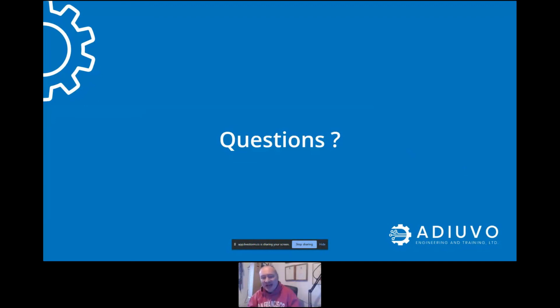Oh, that's a great question. Is there any advantage in using synchronous or asynchronous resets? You're going to have to read the documentation on that, and what I mean by that is you're going to have to read the documentation for whichever FPGA you're targeting. Some families will recommend that you use an asynchronous reset. Some designs will recommend that you use a synchronous reset. It really depends on the architecture that you're implementing in your design.